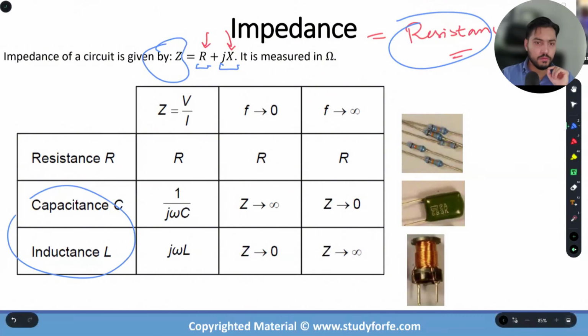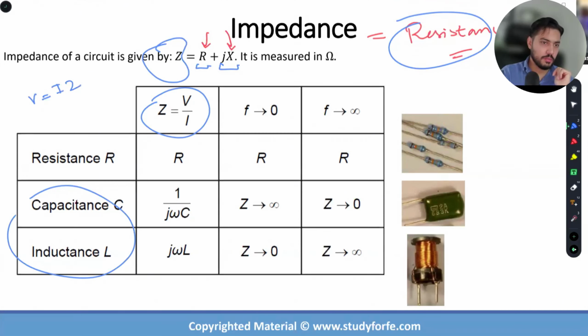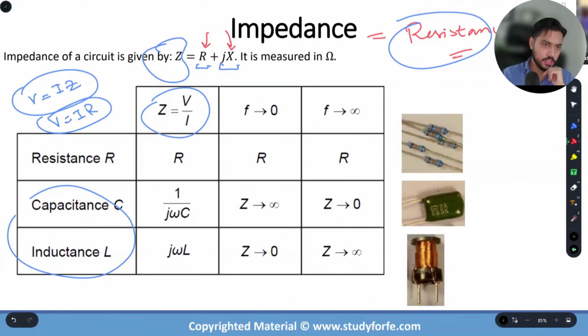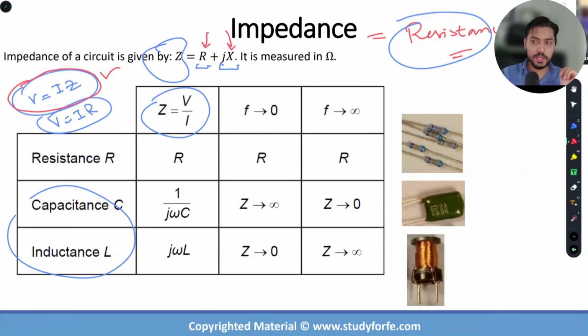Okay, so Ohm's law applies to impedance, it applies to resistance, it applies to reactance. Okay, V over I. To cover all the bases, Ohm's law is stated as V is equal to I times Z. The more simplistic, more common definition is V is equal to IR, but the more accurate one, the one that captures all the different scenarios, is this definition, because the impedance that you have may only be purely resistive, or it could also have a reactive component to it.